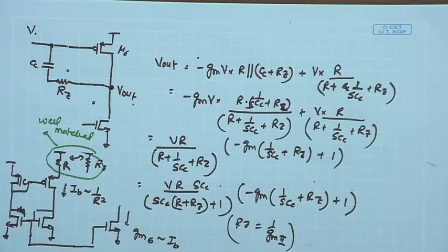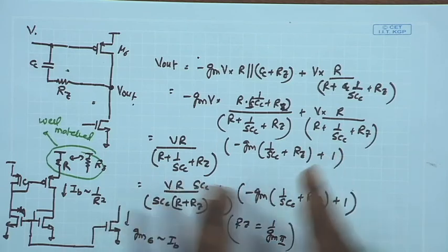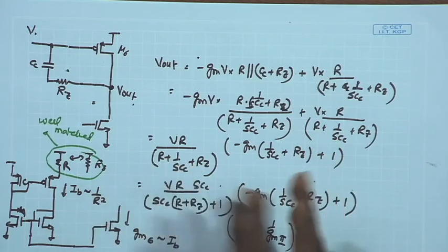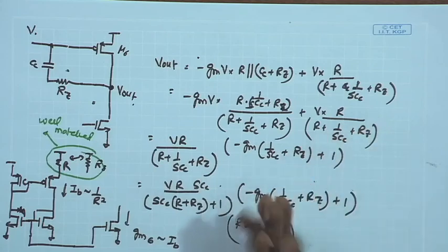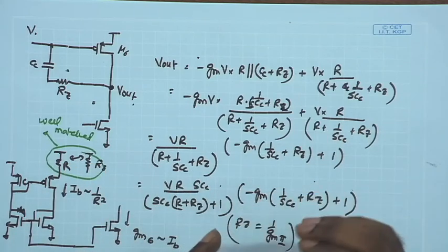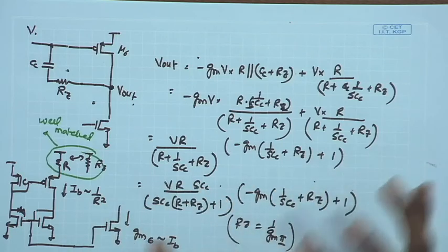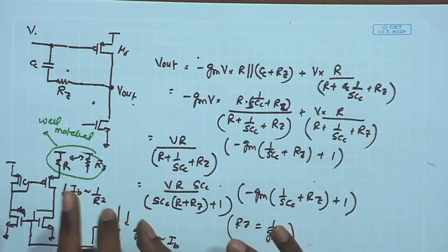You have to look at the frequency compensation, you have to make sure that you are using a 45-degree phase margin by inserting capacitances at proper point, and make sure that whatever compensation etc. you are doing, it is robust enough, it is not failing at different process and temperatures. So that is another important point. Apart from that, whatever we do in the noise analysis part or DC biasing part, the similar concepts apply in other circuit topologies also.